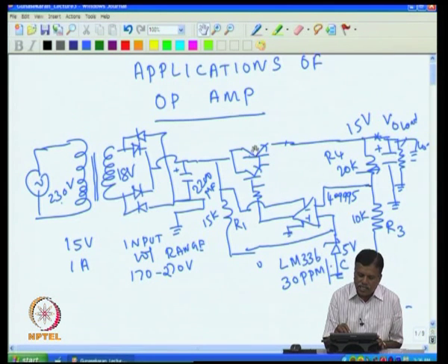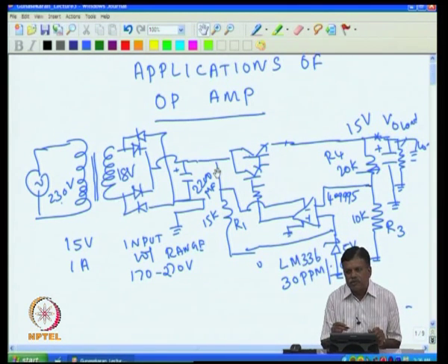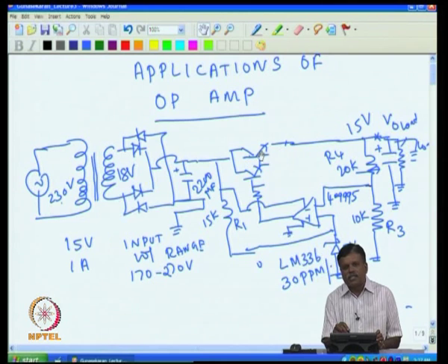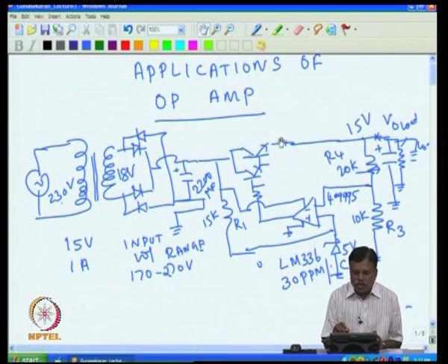When this transistor is heated up, then inside the connecting wires and then the silicon, everything heated up, and they are all stretched, and when it cools down it comes back. Every time when heating and cooling, there is a thermal fatigue develops inside. Then after several cycles, the wire bonding actually breaks inside. So, how many thermal cycles the transistor can withstand depends upon how much temperature it went and how much it had come back. So, the delta T is very important.